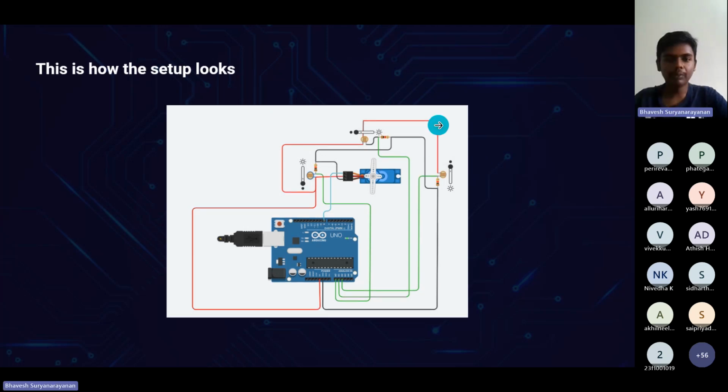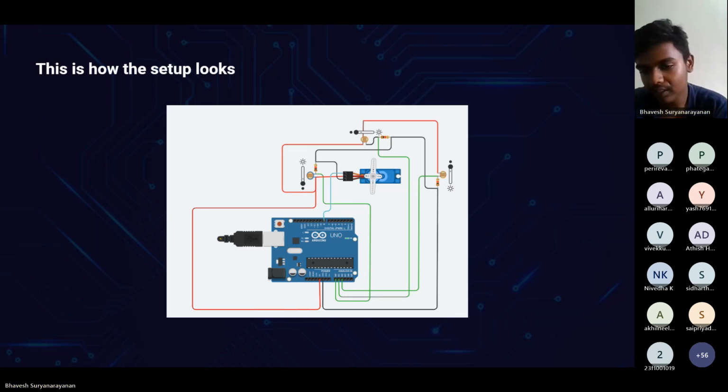Yeah, maybe you can do it, but the better method is you find a formula. You have the three intensities from the photoresistors. You find a formula, or it's actually a simple formula only. It's not so hard. If you think well, I think you'll probably get it. So using that, you find the direction of the sun and you get the angle, right? Using that, you get the angle and you just do servo dot write to that angle.